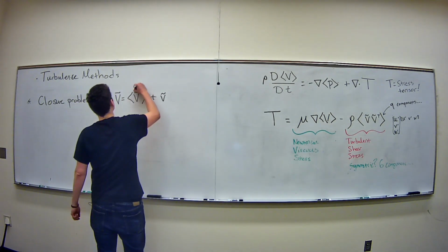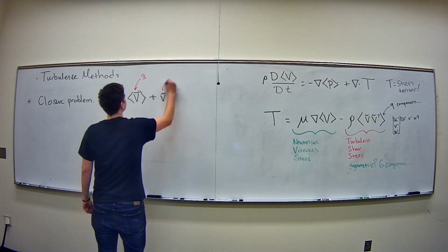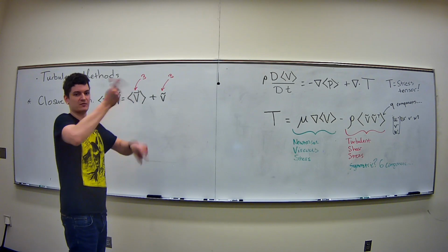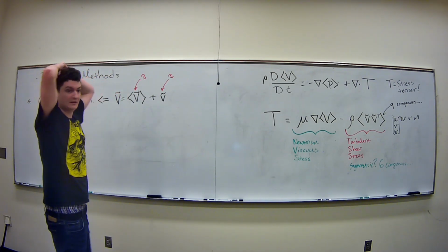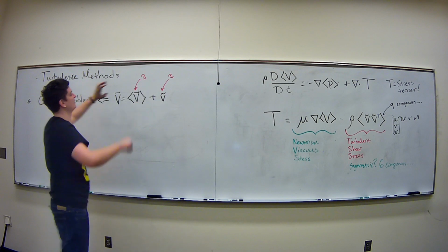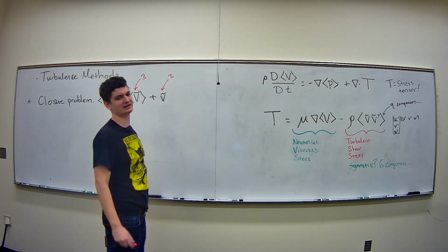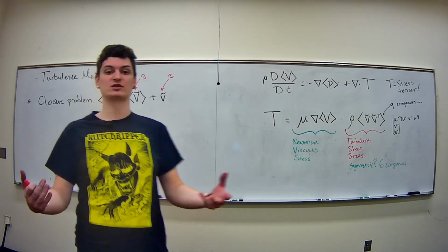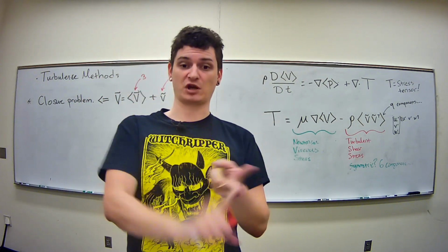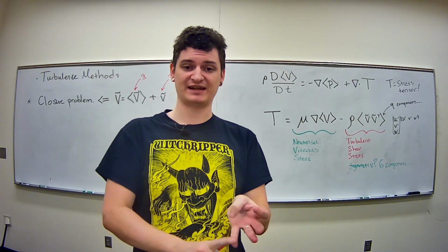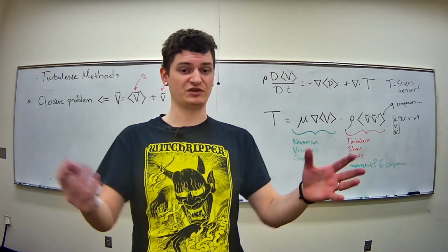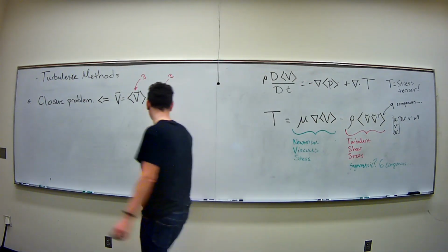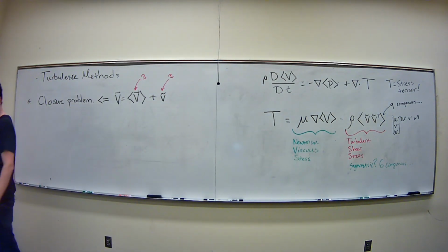Here I have 3 unknowns, and now here I have another 3 unknowns. I don't know the fluctuation in the x, the fluctuation in the y, and the fluctuation in the w, right? So certainly there's a closure problem, right? You introduce 3 more variables. How do you pin these ones down, right? When it wasn't there, when there was no fluctuations, we could close the problem. We could close it by conserving mass, conserving momentum, conserving energy, and an equation of state. We got the 6 equations that we had symbolically, and I showed you how everything's consistent in here. No longer the case because of that friggin' Reynolds stress.